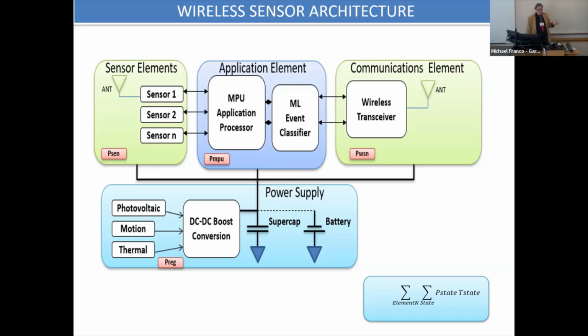Just going back 10 years, to transmit the wireless messages, encoded or digital, to a cellular network, for example, you typically used a 2.5 or 3G network. And the specs on those parts, you have to have 1 amp available when you transmit the message. 1 amp, right? So you're basically down to one thing, and that's a battery. And maybe large photovoltaics will work in that scenario, but it's not.